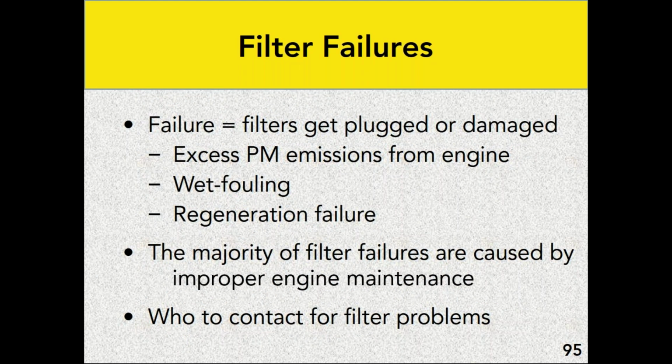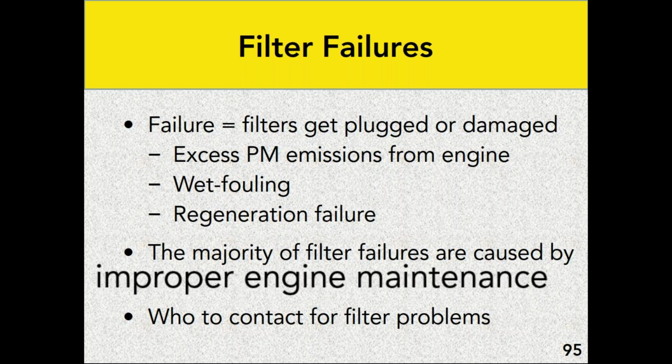We do need to talk a little bit about failures, however, because these filters, even if you're watching, even if you're taking care of them, they can fail. Now, these failures happen when they get plugged or damaged, when there's excessive emissions from the engine, when there's wet fouling, regeneration failures, all of these are causes for a filter failure itself. But generally speaking, improper engine maintenance is what we find is the most common issue when a filter fails.